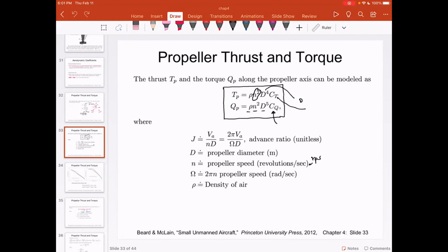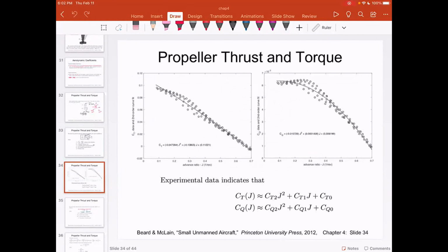Please note prop torque is sort of an unwanted phenomenon that comes into the picture because of Newton's third law. Every action has an equal and opposite reaction. However, when the prop generates a thrust, the reaction thrust acts on the aircraft that propels the aircraft forward. And this equation needs to be programmed in our simulation so that we can run the simulation with realistic prop implementation.